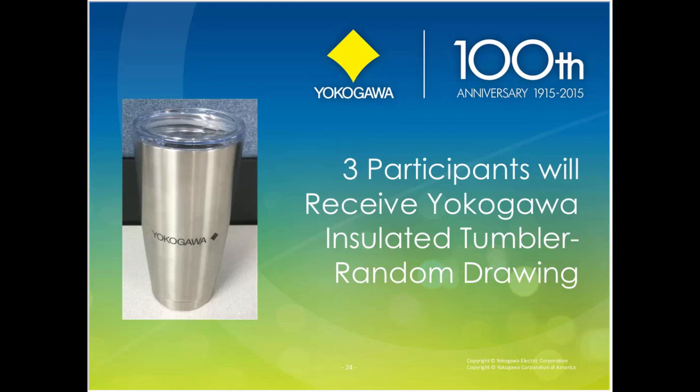Another question came in: how would you test the stability of a thermal well? When would you know it's time to replace the thermal well? If it's possible, you can remove it from the process and visually inspect it. As long as it's not corroding away because of a material compatibility issue, or eroding away from the process hitting it, and you can visually inspect it and make sure it's still intact, then it should be fine. It should last for a significant amount of time. So that was a good question.